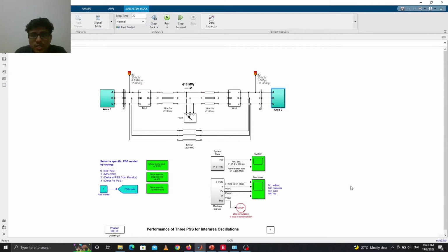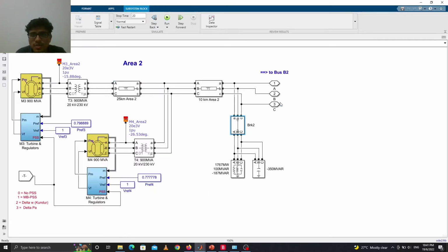So for today, I will give a little presentation about the task that has been given to me, to get a simple waveform for the simulation at bus 9. For accessing the bus 9 circuit, we need to go to area 2, and this is our bus 9. I have changed the circuit a little bit to get the actual result. So over here I add a 3 phase breaker.